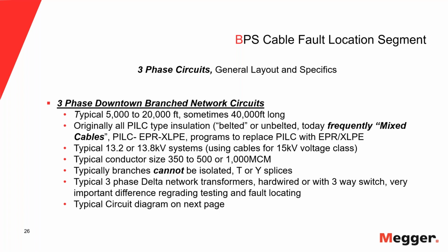Okay, so we have in these systems, like I say, a mix of different type cables, and the voltage is typically only 13.2 or 13.8 in these systems, and so pretty much all these cables are 15 kV class cables. The typical conductor size is between 350 and 500. Sometimes you have also 1000 MCM. Again, it depends on the loads.